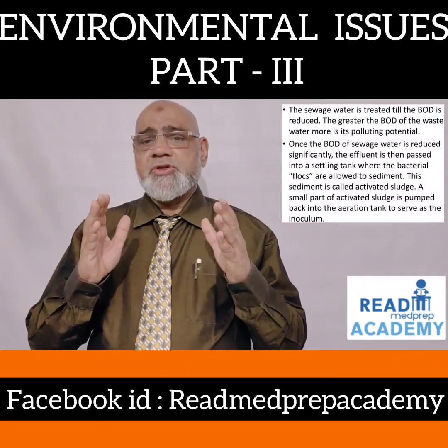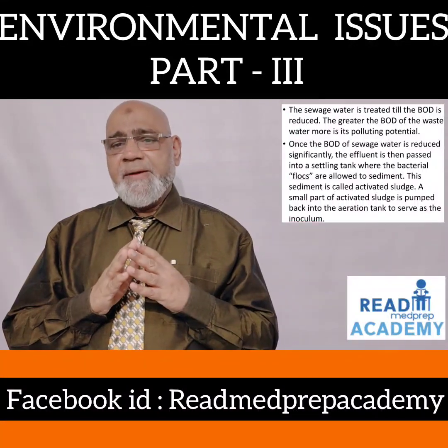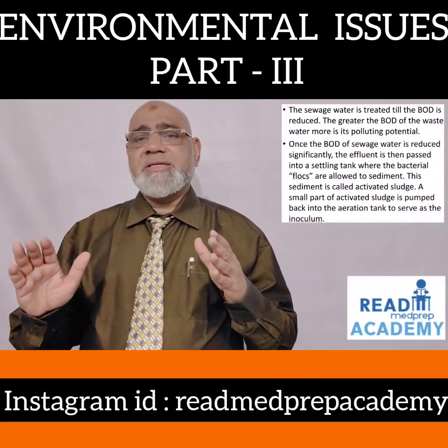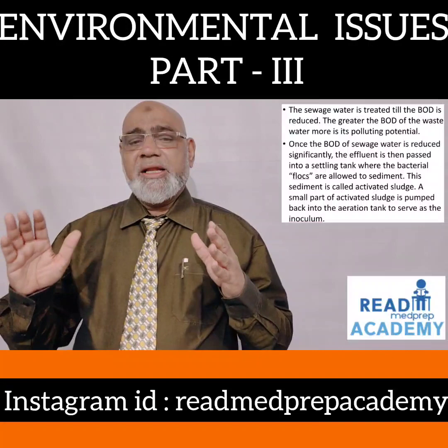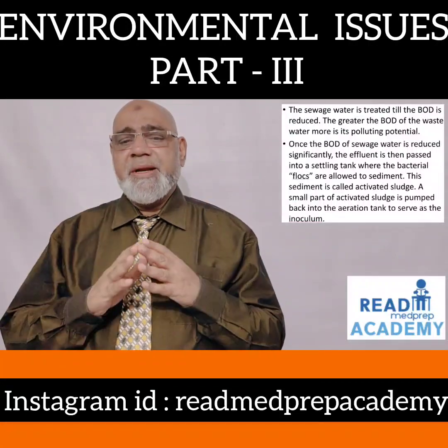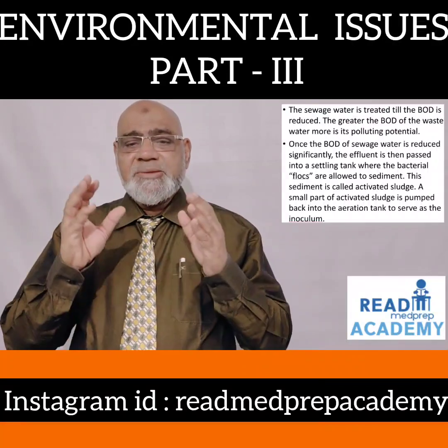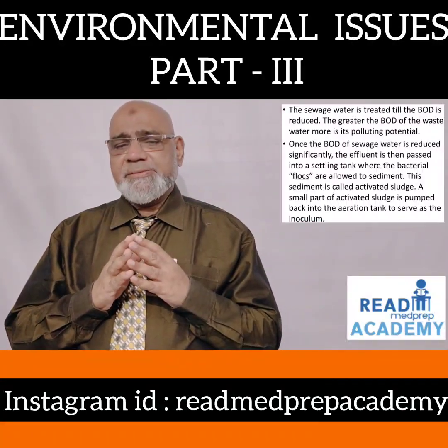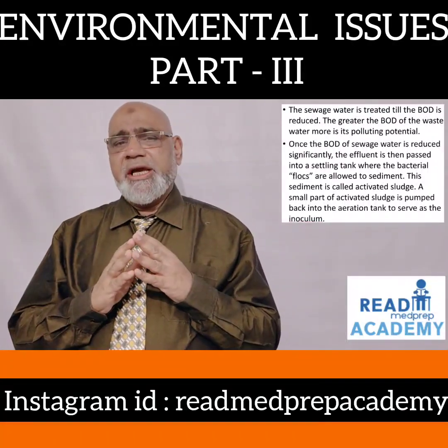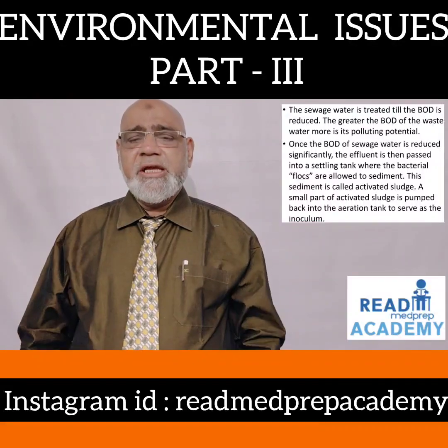Once the BOD of the sewage water is reduced significantly, the effluent is then passed into a settling tank where the bacterial flocks are allowed to sediment. This sediment is called activated sludge. A small part of the activated sludge is pumped back into the aeration tank to serve as the inoculum.